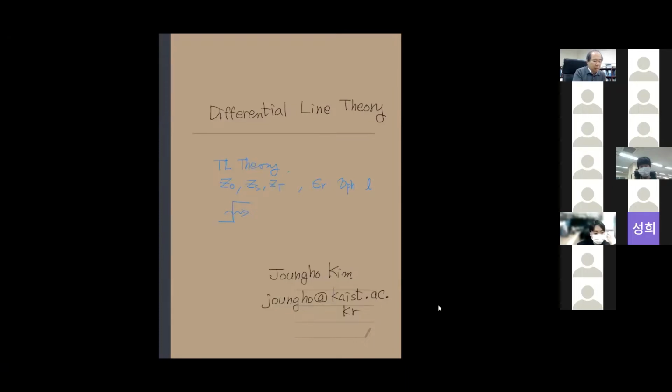But I would like to say that impedance control is really difficult. If we have impedance discontinuities, we will suffer reflections that will cause multiple reflections and time delays and ringings, and it will result in EMI and crosstalk issues. Why do we have difficulty with transmission line impedance continuities? Because our interconnection has three-dimensional structures.